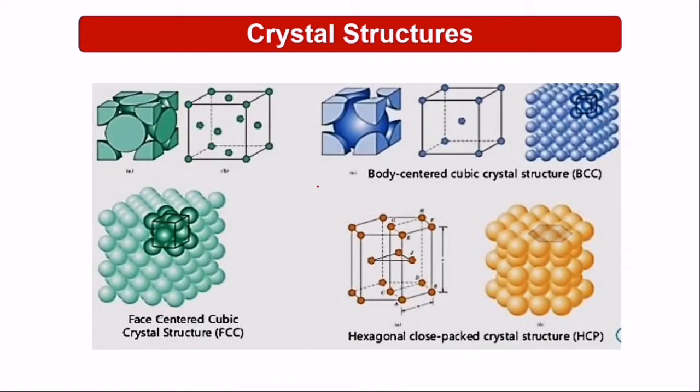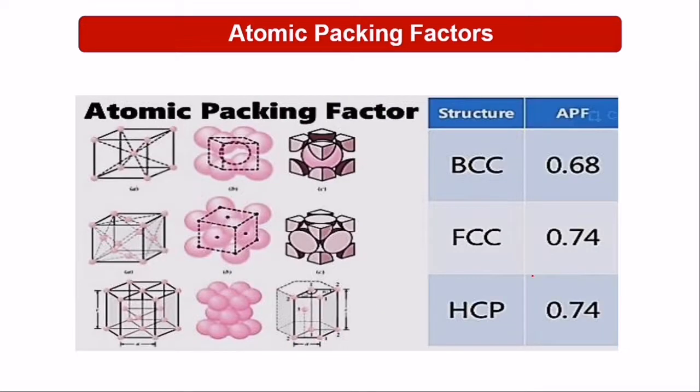Now, from principles of materials, you know that we have some crystal structures. With these crystals, we have the FCC, BCC, the HCP, and the BCT. That's the basic. Is it body-centered tetragonal? Yes, body-centered tetragonal. And also we have the atomic packing factor. The higher the atomic packing factor, the easier the material can be formed. First we have SC, but normally we don't deal with SC. That has an atomic packing factor of 0.52. We have BCC at 0.68, FCC at 0.74, and HCP at 0.74.